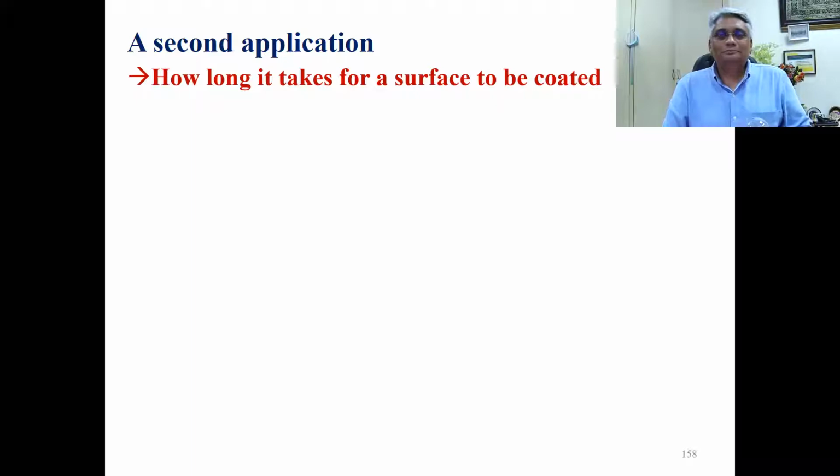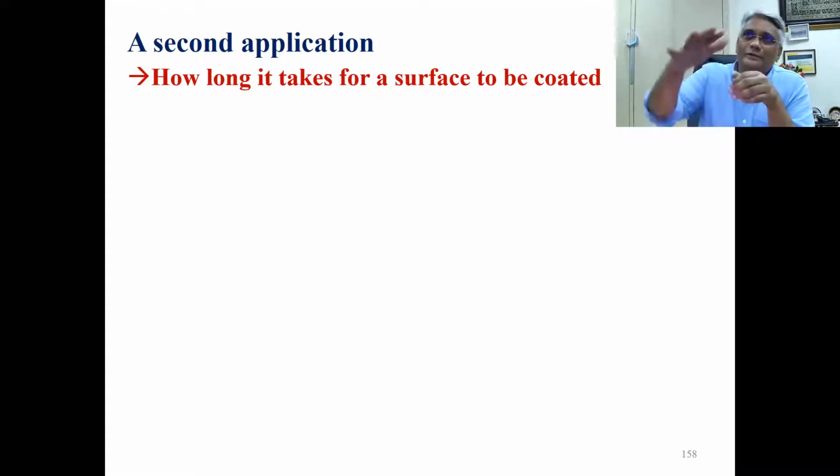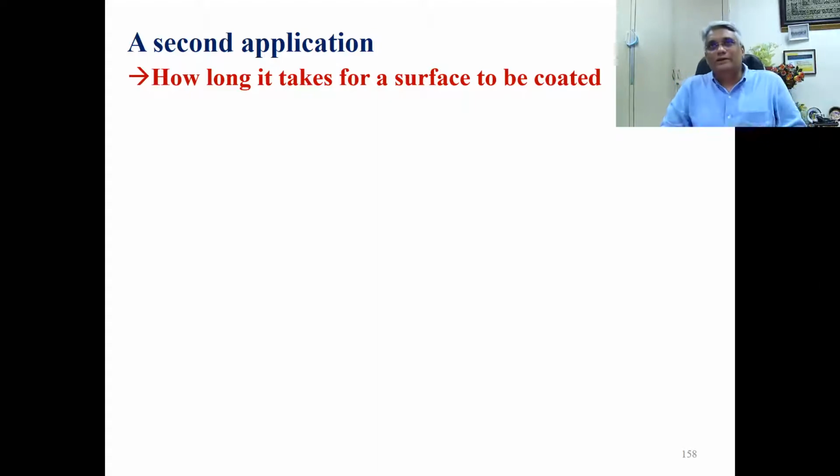When you do that, you need to clean the surface before you put it inside the chamber, and then you start evacuating. You want the deposition to happen on a piece of silicon, which is used as a substrate. So there is a cleaning process involved, because without substrate cleaning, you cannot expect deposition on a pristine, pure surface. So substrate cleaning is always essential.